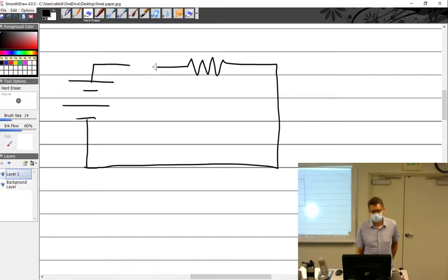Remember this project? Yes. Okay. If I want to know how much current is flowing through here, what do I have to do? Disconnect it and put a what? Now all of the current has to flow through the ammeter. And your Simpson meter can only handle how many amps? 10. So I want in my airplane an ammeter that is not much bigger around than my watch. And I want it to read up to 30 amps. Wish me luck? Okay. There's another way to do this. If I want to know, this doesn't work,